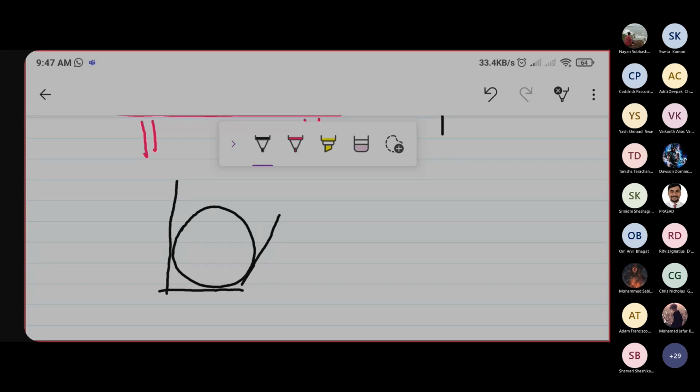This sphere is kept in a trough, and it is in equilibrium. When a body is in equilibrium, we can remove all supports, and instead of those supports we can show them by using forces. So let's do it one by one. First draw the sphere. Let's keep the body as it is. Forces are acting on the body, so let's remove the supports one by one.